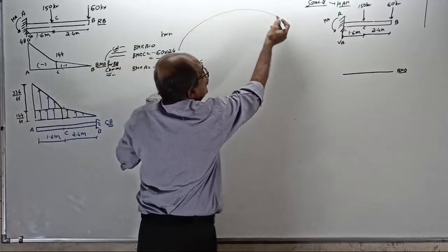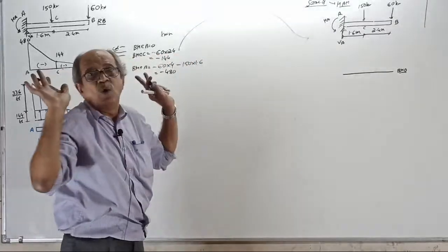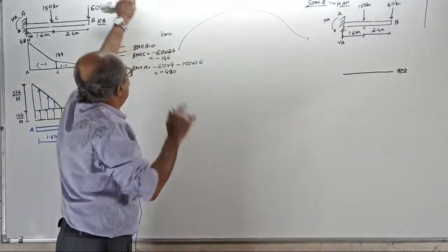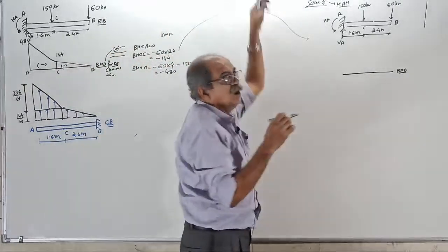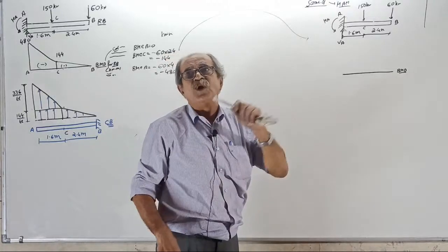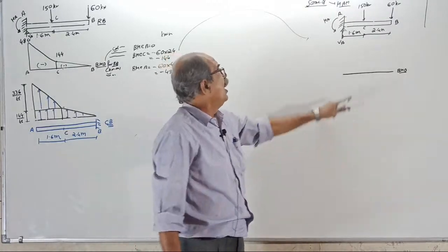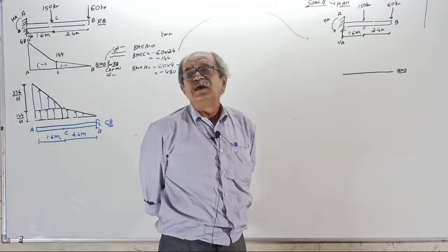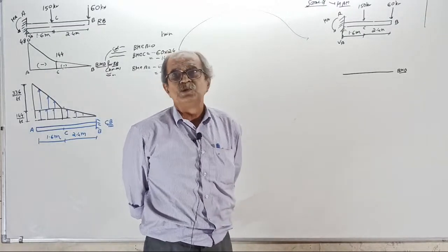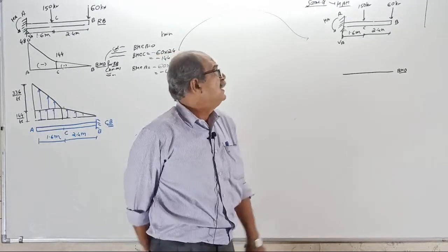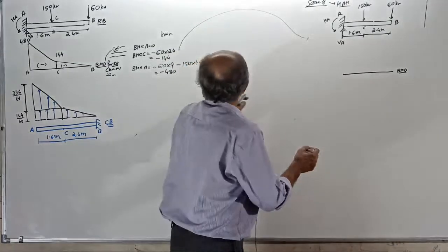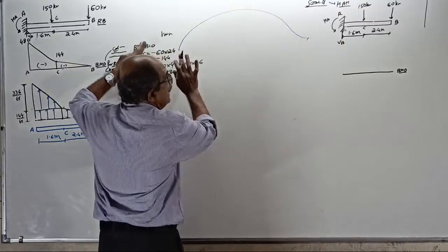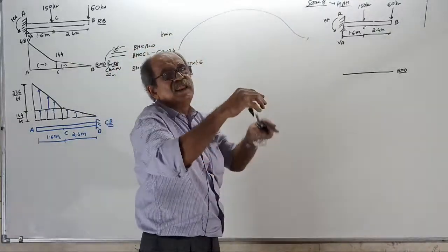Same calculation for moment area method also. Now, if it is moment area method, draw the BMD. I told you, do not use sign for BMD. Why? Because in moment area method, the direction of slope and direction of deflection we decide by the elastic curve. Therefore, while calculating, the sign is minus; usually people write minus below the line.